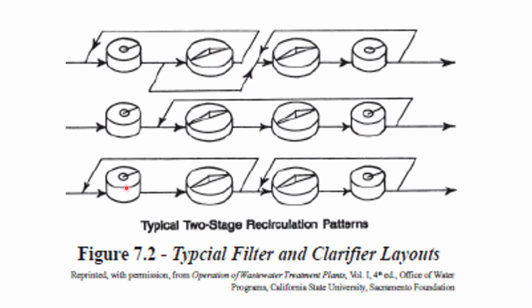And in this one, same kind of thing, a little simpler than the first configuration up here. By virtue of the fact we're recirculating the outlet of the first trickling filter back to the primary clarifier, we're getting rid of some more suspended solids, and then we're passing it on along to the second trickling filter, and then we're getting rid of some more dissolved organic loading.